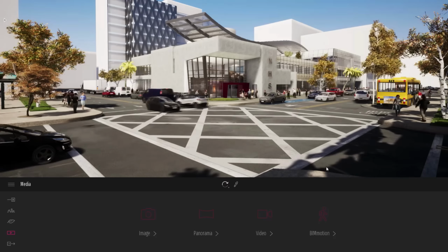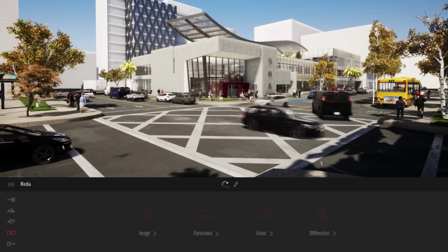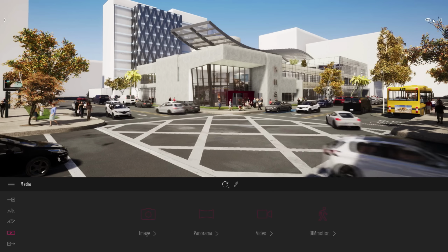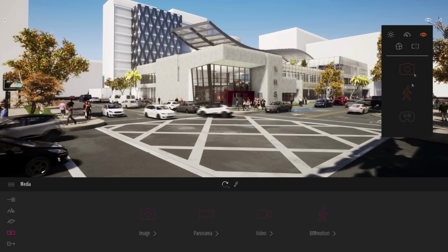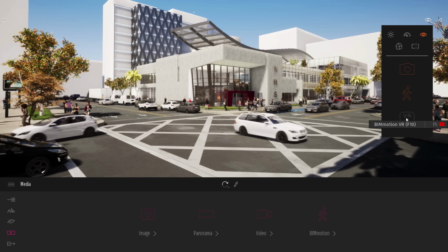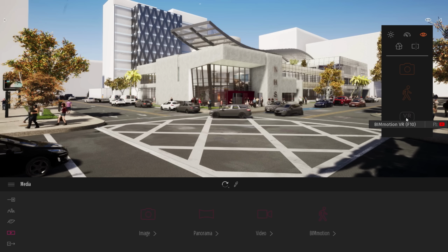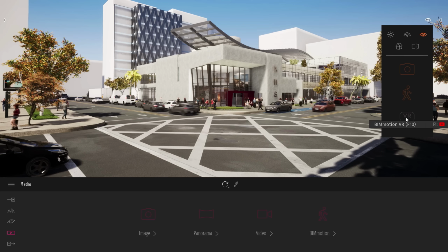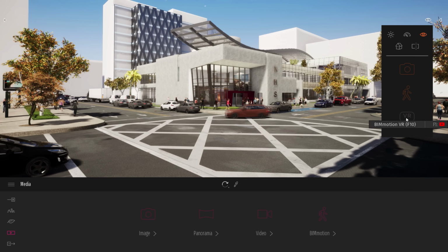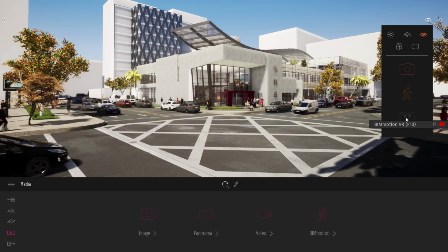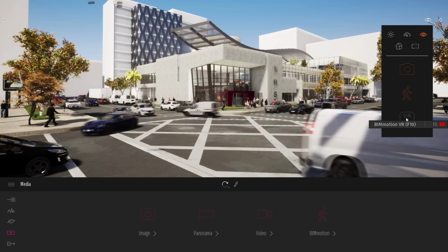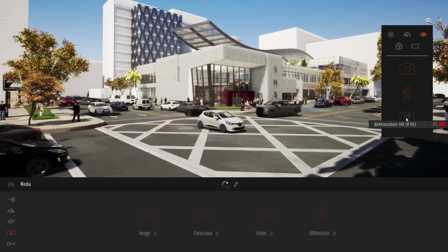Also, what is most important with Twinmotion is that at any time we can switch to virtual reality. Here I don't have any headset plugged in, but as you can see, it's just a basic shortcut, F10, to switch to VR. So going from ARCHICAD to Twinmotion is done in 1-2 clicks, and then from Twinmotion switching to virtual reality is done in only 1 click.